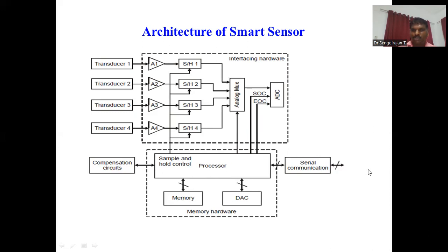to the output. So the smart transducer involves various blocks such as capturing the signals, comparing the signals, removing noise and distortions, and amplifying the signal, where it is interfaced with the interfacing circuits. All these are conversions from analog to digital signals, and the digital signals are communicated through serial communication protocols. So this is called a smart transducer.